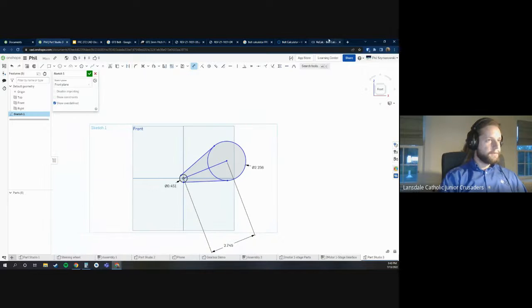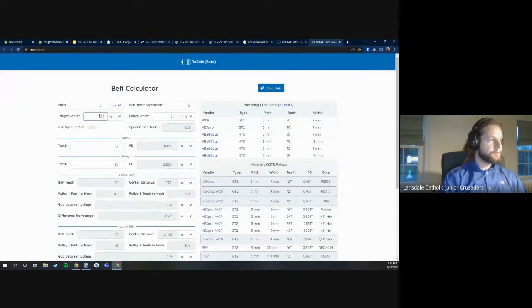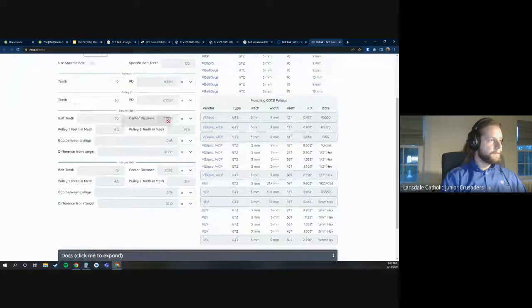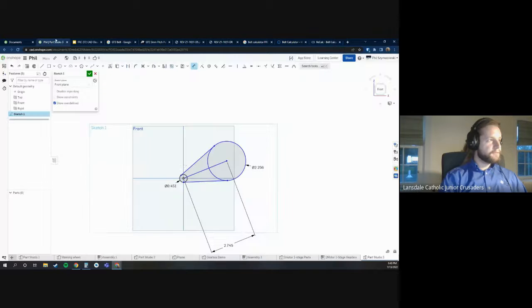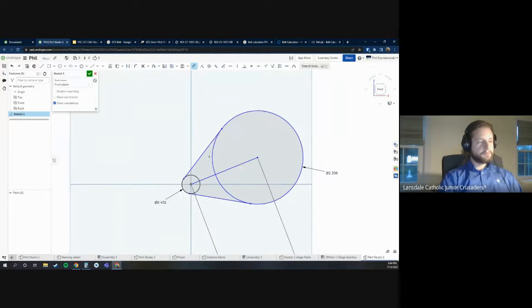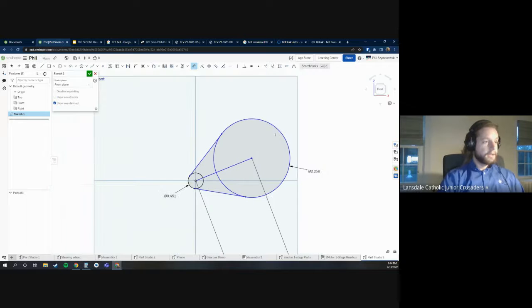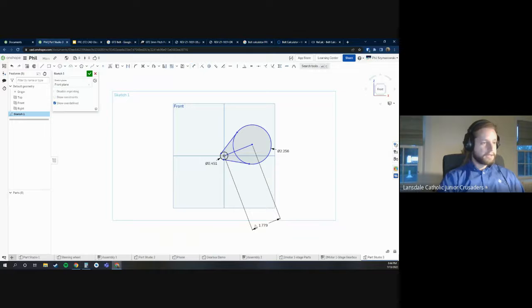And I wonder if I could use a smaller belt. What if we used a smaller belt? What if we went to 2 inches? We went to 2 inches, our center becomes 1.7791. So I'm going to try that. And the reason why I'm trying to go smaller is because maybe I'm trying to minimize the overall size of my gearbox. And that seems like a reasonable way to go.